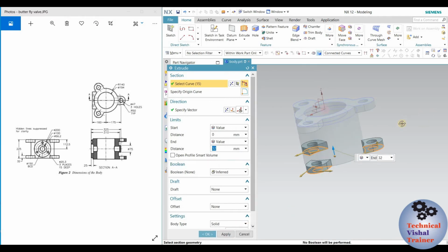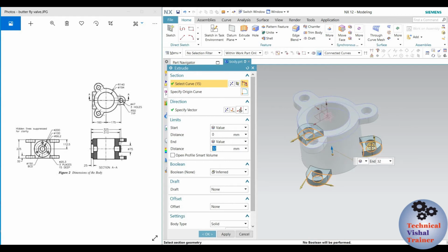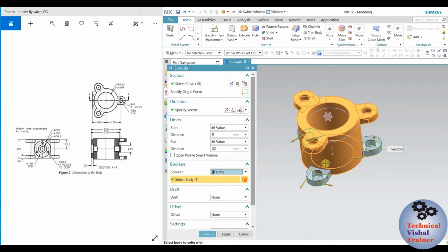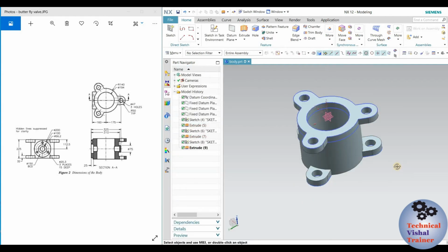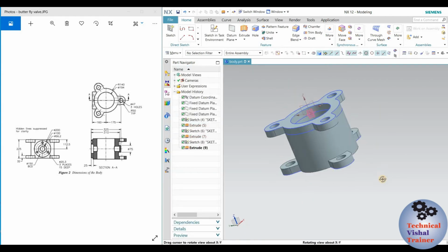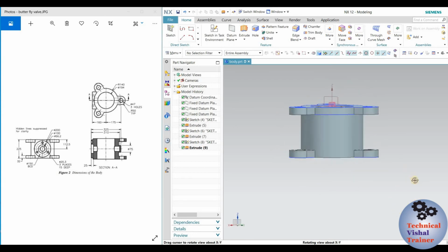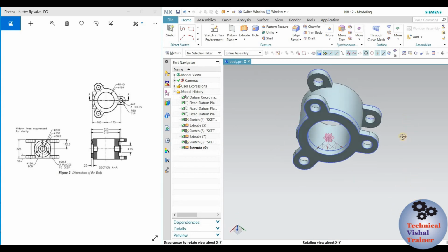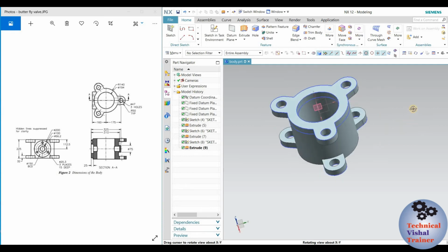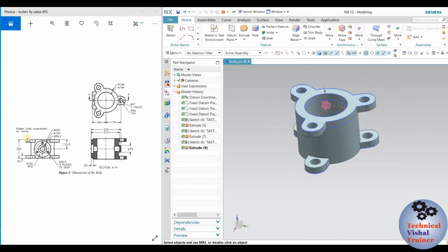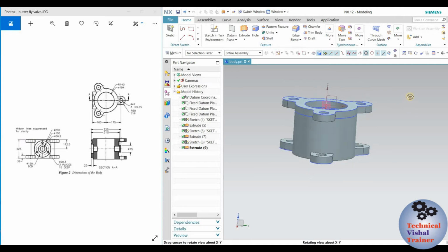So whenever we are going to make this as this one, we have to perform what? Boolean operation. It should get unite. Every time I say it should get unite with the base one. So are you getting what I am trying to say? I have created this now. So now I want to see whether I have created the correct depth or not, that is this 225, whether I have specified the exact dimension or not.